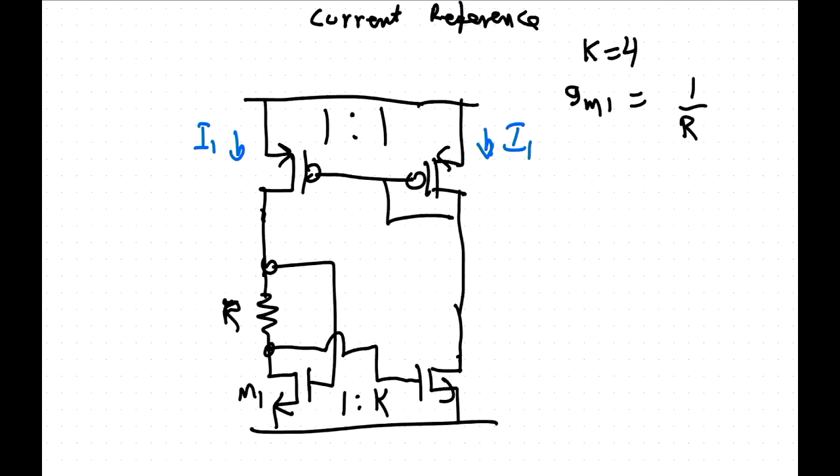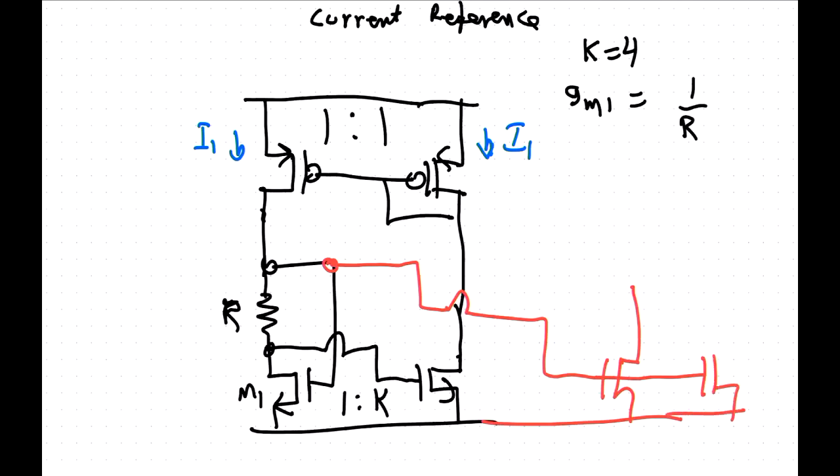Now, that is important, because what you can do now is use this one here as the output and have lots of current mirrors hanging off here to do your biasing. If you derive all of your currents from this source here, you know how the transconductance scales with current and how it scales with transistor dimensions.